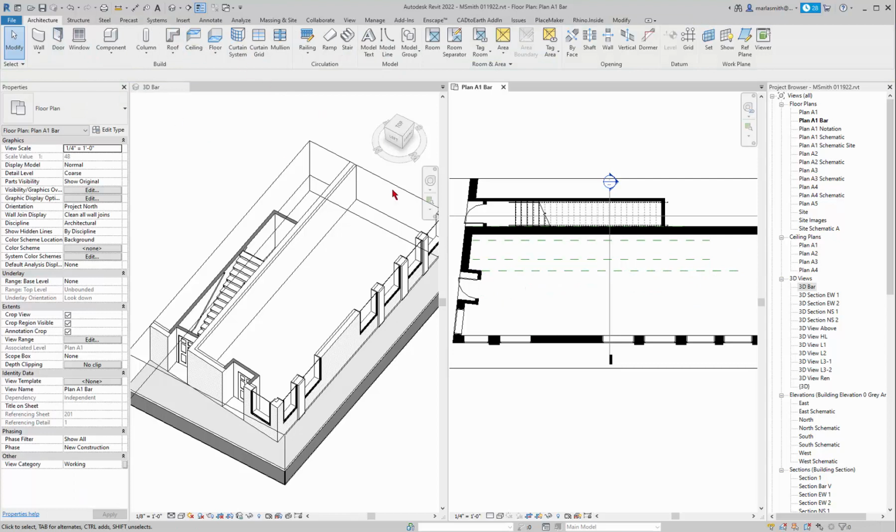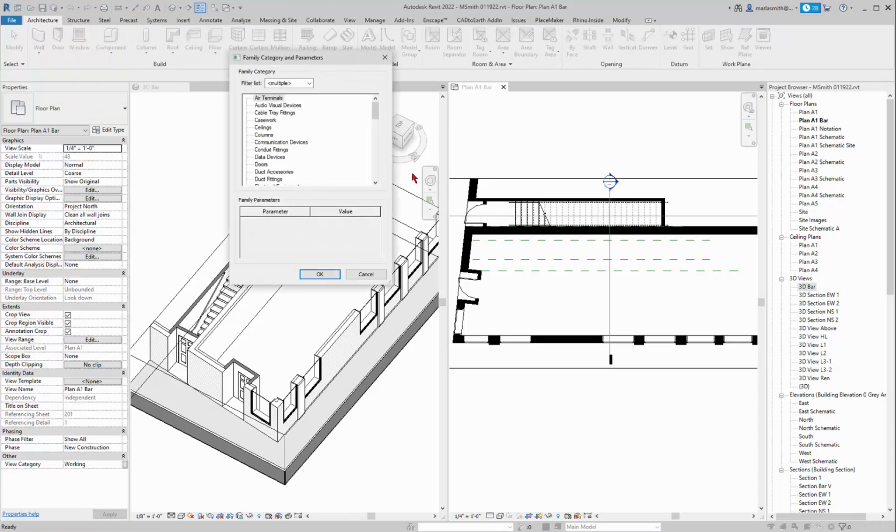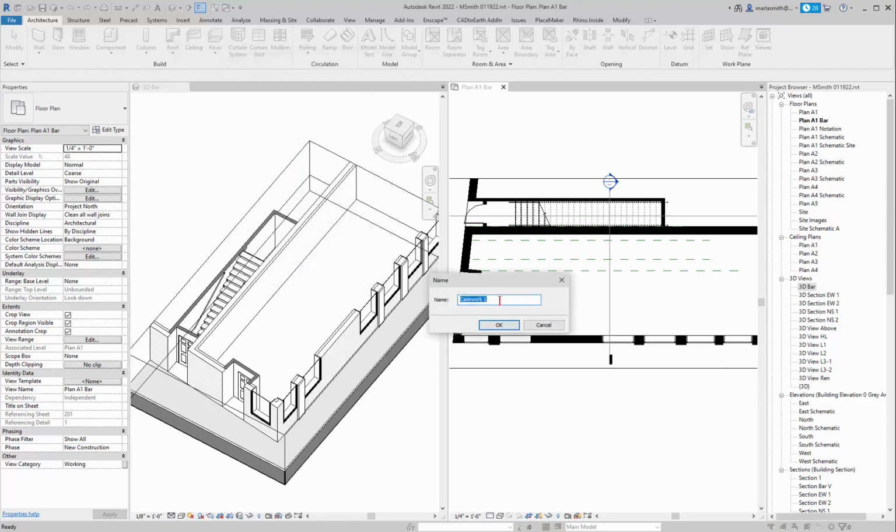So at this point I'm kind of ready, and notice that Revit requires a bit of setup, right? So I'm just kind of getting things set up. You don't have to do this, but it does help to know kind of scale wise where you're working. And so what I want to do is I wanted to go to the component now and model in place. You worked in this with the masses a little bit, but if you go to component model in place, instead of mass, you want to pick casework, because that's basically what most millwork and cabinetry and all that kind of stuff is set to. So I'm going to pick casework there and click OK. And I'll name this bar design for right now.